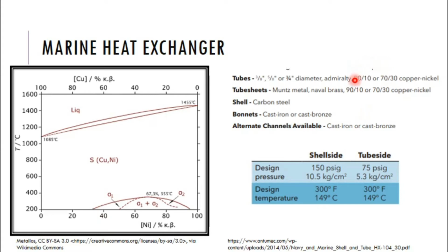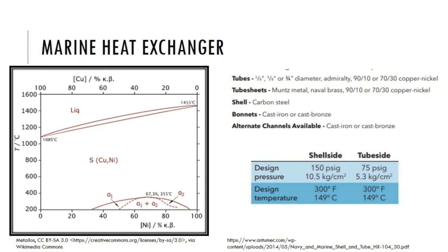At different temperatures, the microstructure that results from these differing alloys depends on the phases present in that particular alloy. This equilibrium diagram is up to only 200 degrees Celsius, but even at this point the phase present is a solid copper nickel. At the 70-30 copper nickel, we see some semblance of a transition between the alpha 1 phase and the solid phase. Hence the microstructure at 70-30 would probably be different from that at the 90-10 alloy.